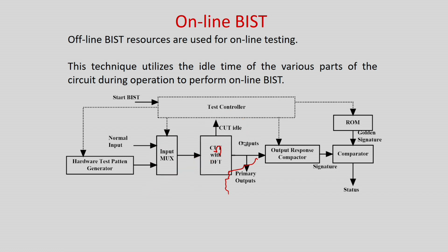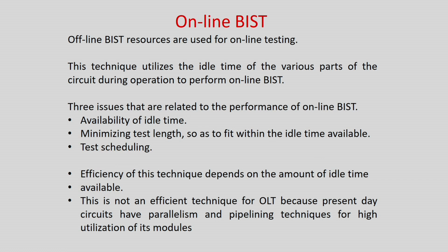But this is not very popular. Initially it was very popular, because you can basically use the normal BIST to do both online and offline. So it was very good and very well appreciated. But nowadays this popularity is going down, because it totally depends on the idle time. If the circuit's idle time is very less, you cannot even test the circuit properly, because only when the circuit is idle can you apply the BIST, because in online testing you cannot stop the inputs.